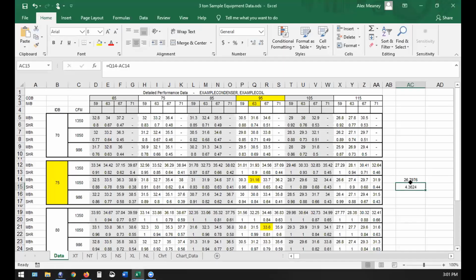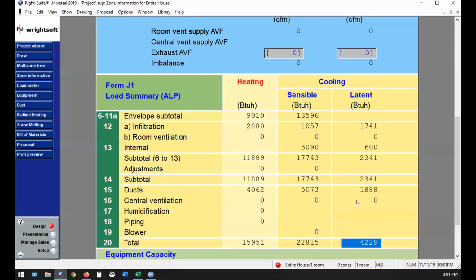And it has almost 27,000 BTUs of temperature control, which would be 5,000 BTUs more than I need here. And so what would happen is it would satisfy the thermostat prematurely, never run for an hour, and never be able to give me those 4,300 BTUs of moisture removal. So that system isn't going to work. So it would have a huge impact, particularly on this number.